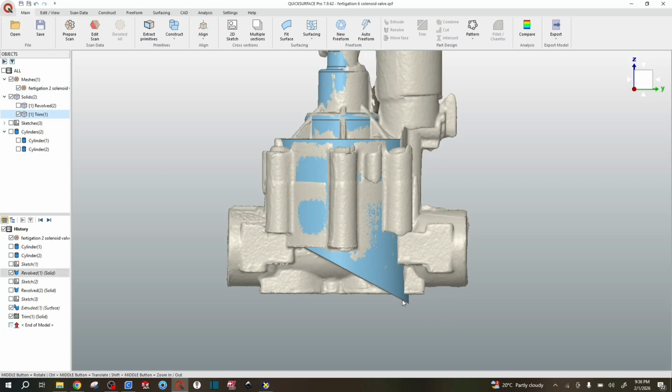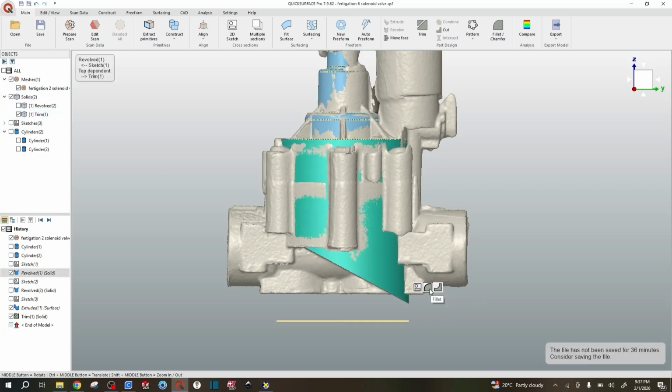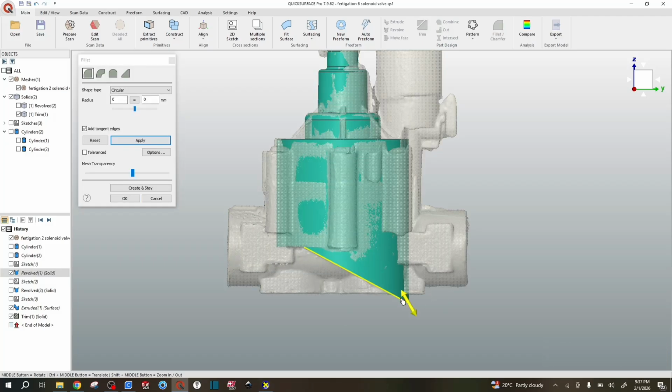that, and then click on it, and you can see that once you highlight these, three icons are selected. You can either start a sketch, 2D sketch, a fillet, or a cut from solid. So we're going to use a fillet, and then you're going to select that edge, and then dynamically just try and get it as closely as we can to the original. So let's say somewhere there. Right there.